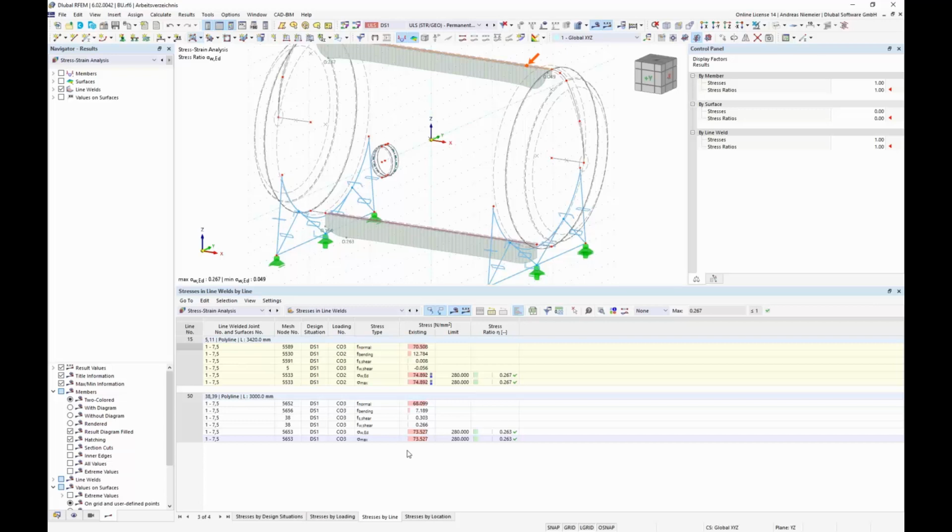So now I want to open the question, why does the program stress-strain analysis mention the word strain? At the moment we take care only about stresses, and the answer is it checks also strains. We only have to activate it.